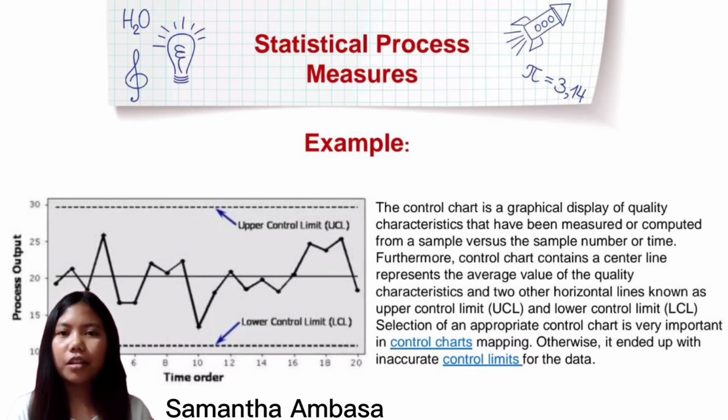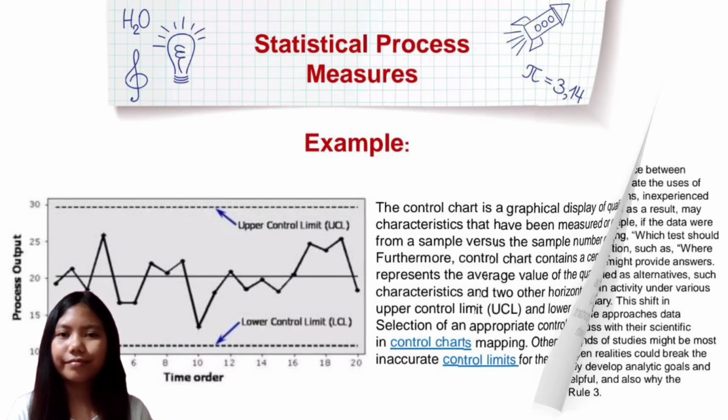And last, 7. Monitor process variation. Interpret the control chart and check whether any point is out of control or shows a pattern. For example, check the X bar R chart. If the process is not controlled, then identify the assignable causes and address the issue. This is an ongoing process to monitor the process variation.